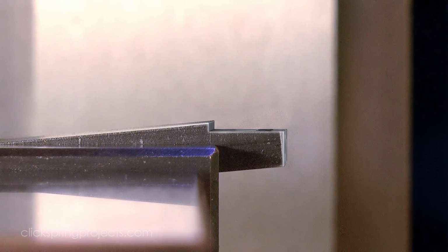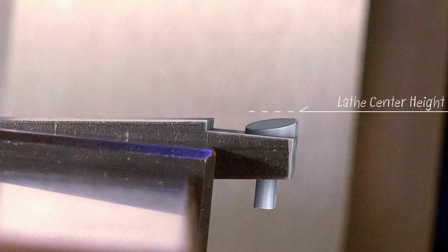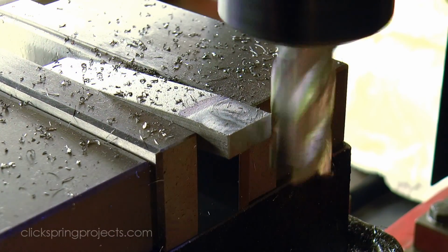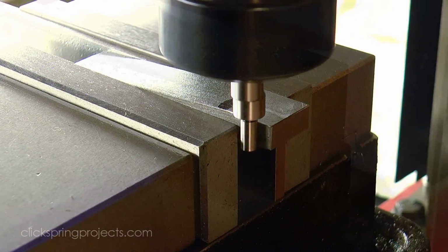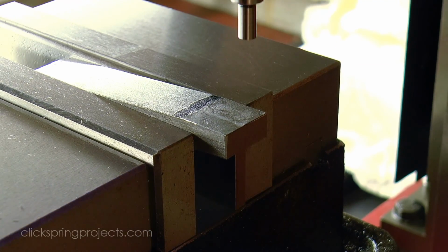And keep in mind that depending on your lathe centre height, there may be an issue in getting the button cutters low enough in the tool holders, so you may find that you need to mill the platform a little deeper to make it all work. As it happens, my lathe centre height is such that I can get away with just taking a small cut off the top, before dropping in the holes for the button cutters.